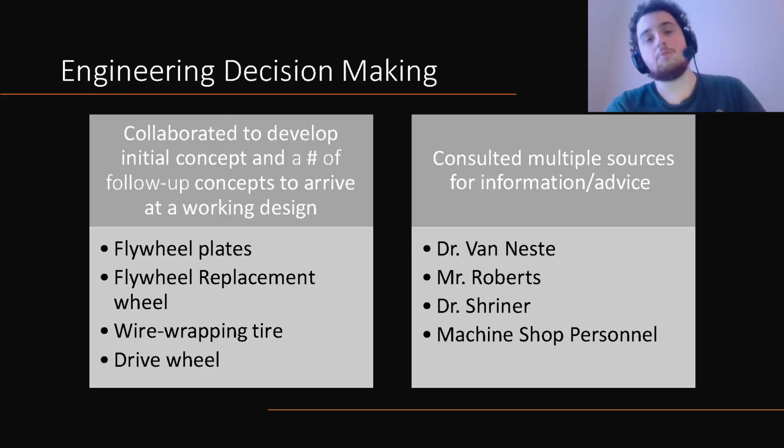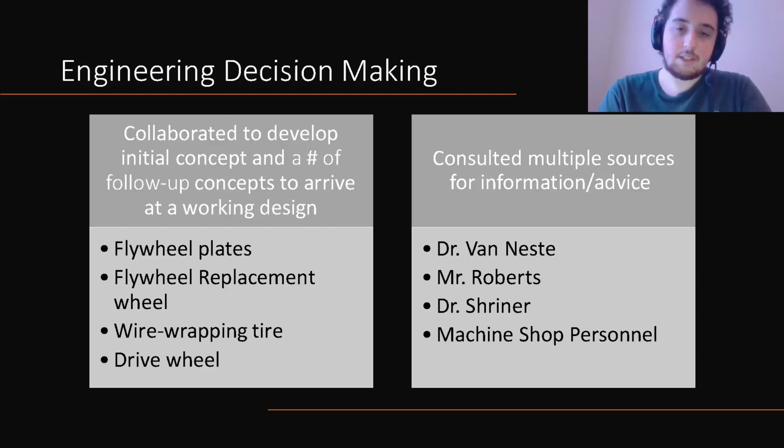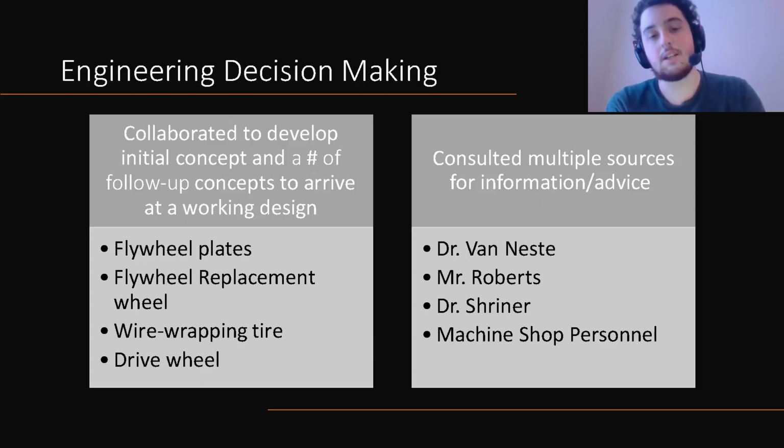The flywheel, when the rider is pedaling, spins at a much faster rate than the actual bike tire, so this will be able to generate a lot more torque. As eddy currents work, the faster the wheel's turning and the closer the magnets are, the more torque's produced. So if you've got a little flywheel moving really, really fast, you can generate lots of torque, and then that torque is converted to the main bike tire through the gearing ratio.